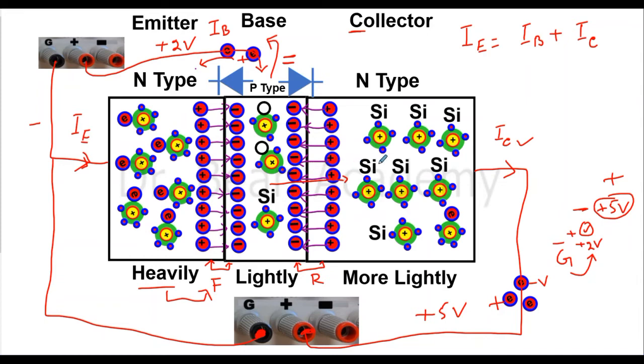And we see a huge amount of current from the collector, because they just go straight towards the collector. And that's why we can write that the emitter current is divided into two sections. A small fraction goes to the base, and it becomes a current from the base, and then we get the rest of the current from the collector.